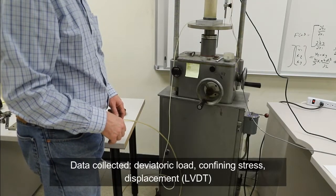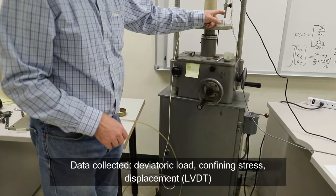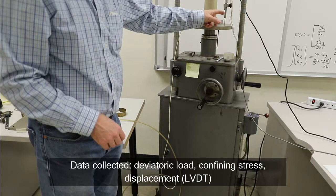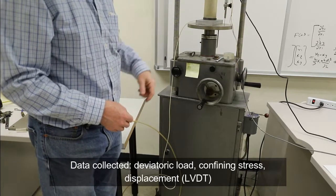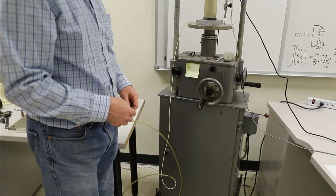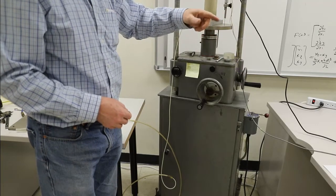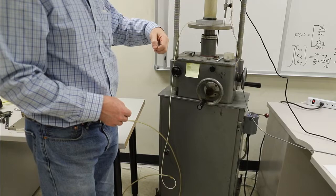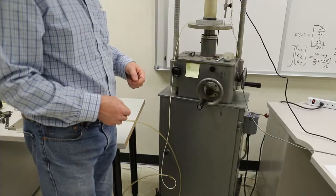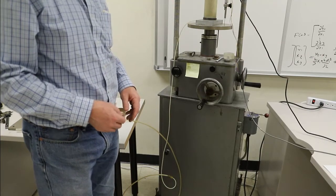The other piece of instrumentation is this linear variable differential transformer, or LVDT. And that's a displacement measuring device. We'll talk about how these different instruments work in a future lab or lecture. But they're both electronic devices, so they're being powered and calibrated by a signal conditioner, so we can have the calibration that we want, and then the signal conditioner converts the signal to a DC voltage, which makes it easy to record on a computer.